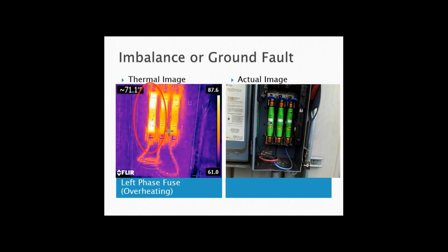One of the things that can blow a fuse is ground faults, such as in motors or other components. So to identify what ground fault I had, I chose and selected a megohmmeter to see exactly which component inside the air conditioner may be defective. So I mega-ohmed all of my motors, essentially. And I also checked my capacitors and contactors for grounds also. Well, during that investigation, I didn't find any grounds.